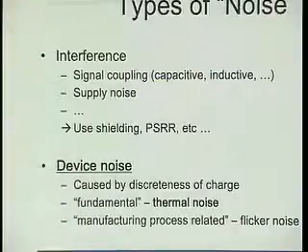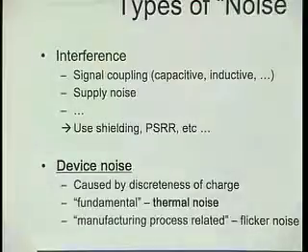Supply noise, obviously, right? I mean, that's again a thing like in SPICE. In SPICE, the ground node, right? We make node 0, and it's supposed to be quiet. In fact, if you build a digital processor, a CMOS processor, Pentium or so, how much do you think ground or VSS is going to bounce up and down as this thing is running? A millivolt? A microvolt? Unmeasurable?